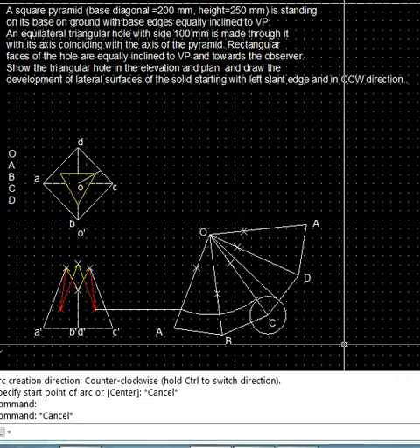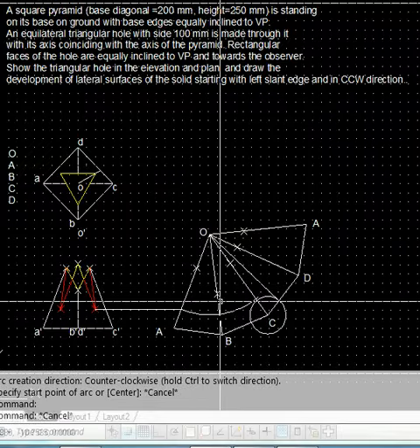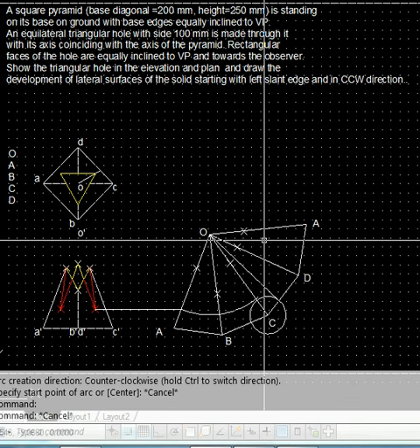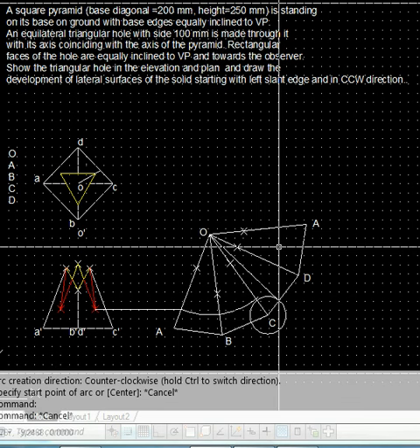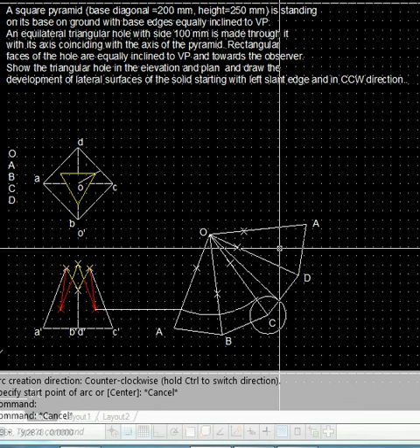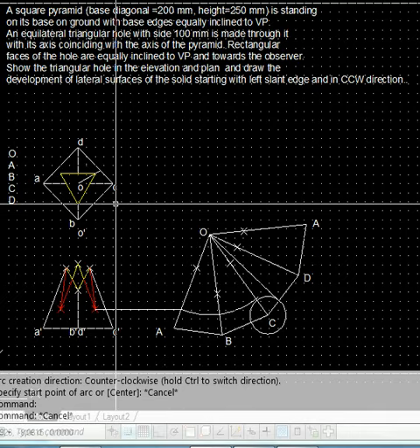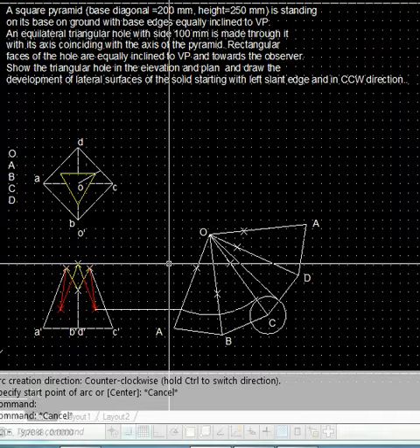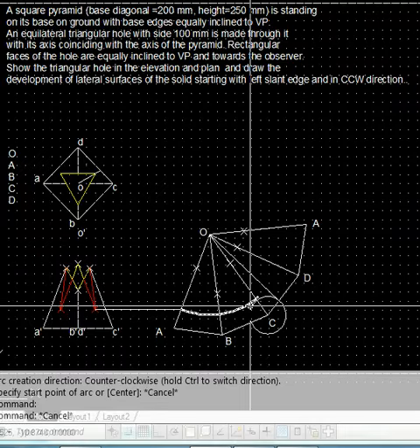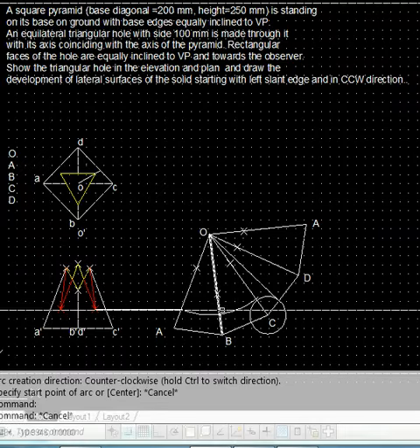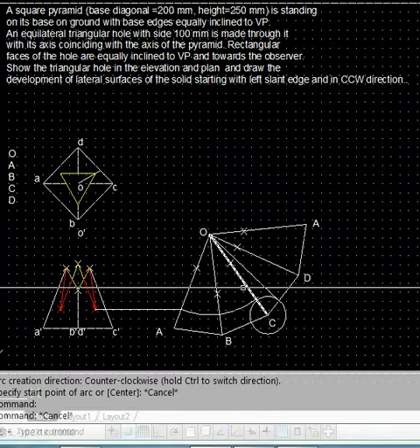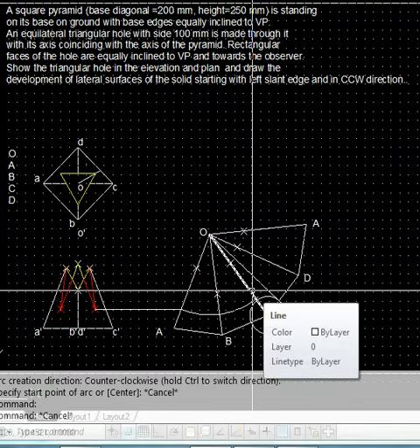So we have used the arc to transfer all these points which are there on the slant edges. But in the development of the pyramid, if the point is lying on the slant faces, for that we will need a line parallel to the base. So we can reach up to the nearest slant edge, that is OC.